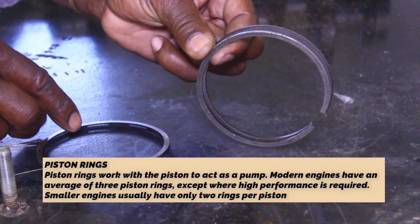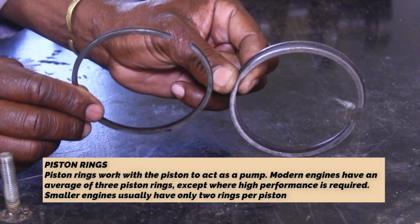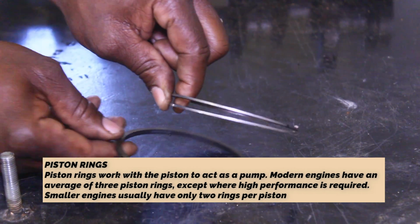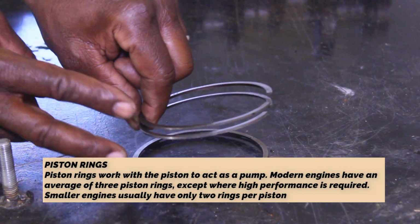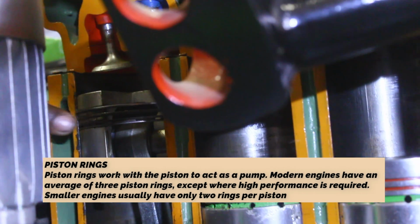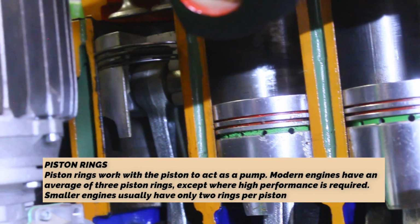Piston rings. Piston rings work with the piston to act as a pump. Modern engines have an average of 3 piston rings, except where high performance is required. Smaller engines usually have only 2 rings per piston.